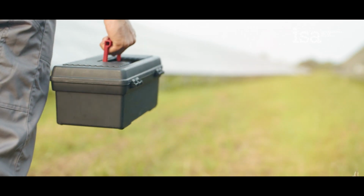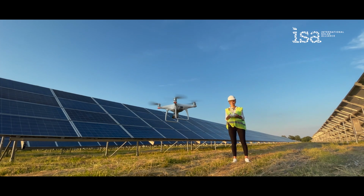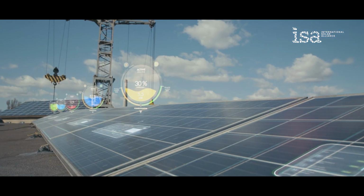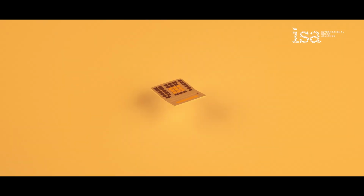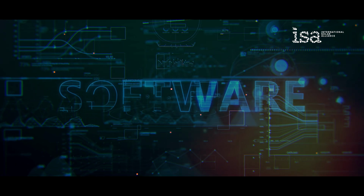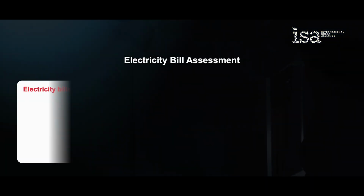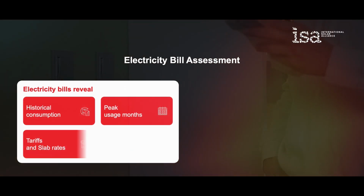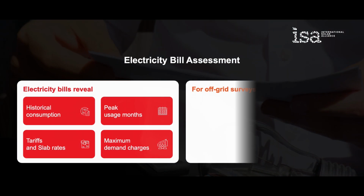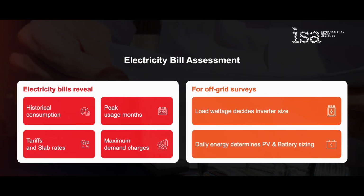Tools help ensure accurate, reliable, and standardized surveys. Physical tools: measuring tape, laser rangefinder, compass, drone for mapping large sites, clinometer or tilt meter. Digital tools: sun path diagram mobile apps, solar irradiation calculators, shadow analysis software, satellite maps and GIS tools. Electricity bill assessment: electricity bills reveal historical consumption, peak usage months, tariffs and slab rates, maximum demand charges. For off-grid surveys, load wattage decides inverter size, daily energy determines PV and battery sizing.